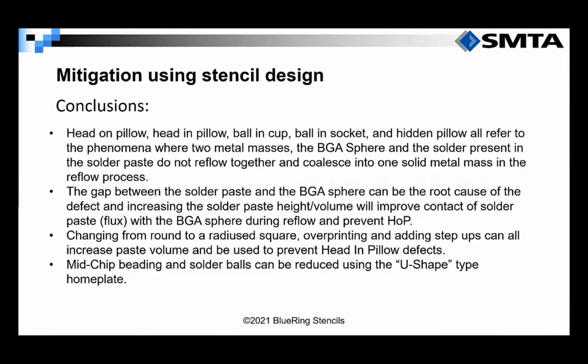And using a rounded square and/or overprinting will also contribute to adding more volume and height during the reflow process. Finally, using the micromachining process to create step-up stencils may be another alternative in gaining additional volume and height during the reflow process, which will prevent this defect from occurring.